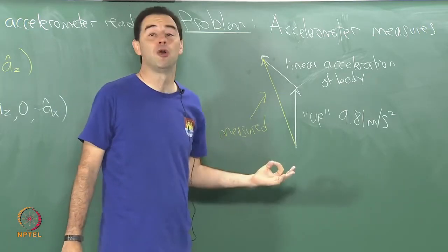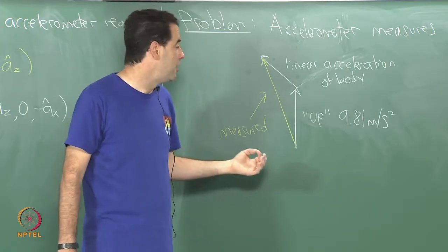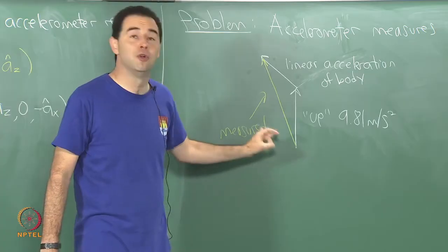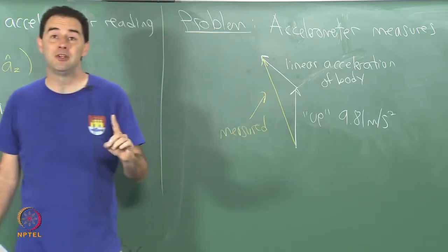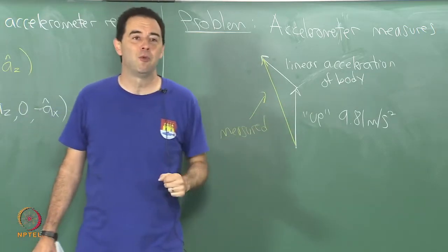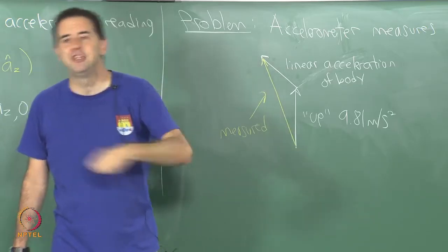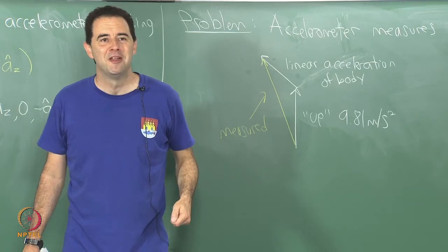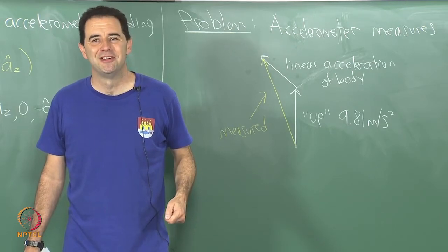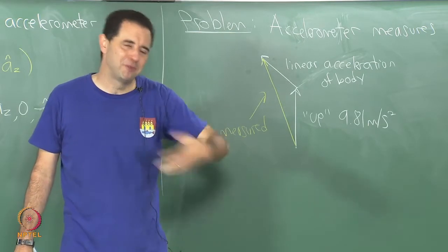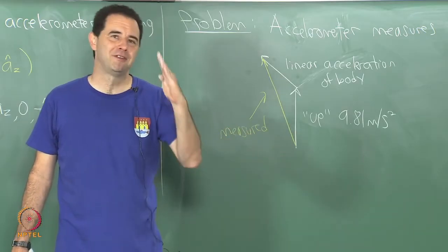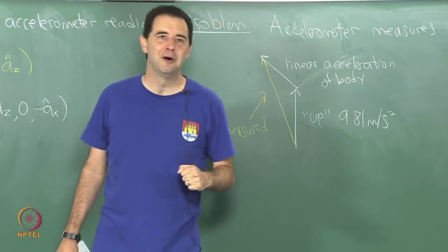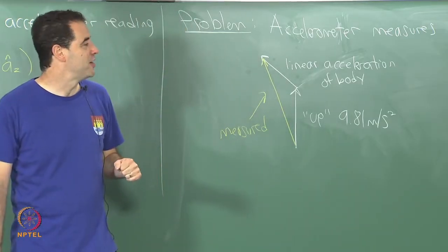So you could give very low confidence or rule out very unusual accelerometer readings that seem to indicate that up is, say, 30 degrees off from what you once believed. Now, if the person continues moving their head very wildly and violently for a very long period of time, there may be no good way to compensate. And you may be able to fool the system into believing that there's a significant amount of tilt before it's able to correct that. So that's one of the strange outcomes of that.